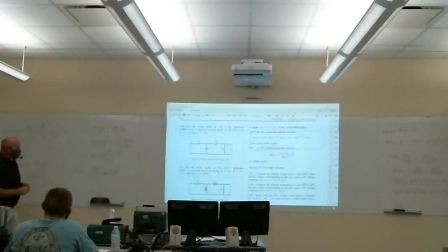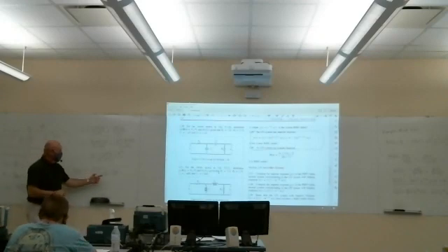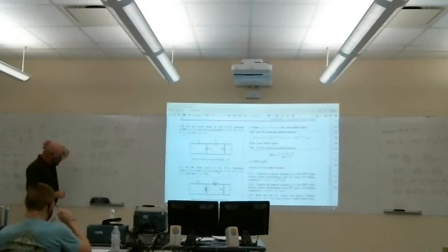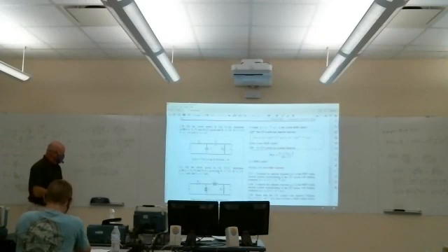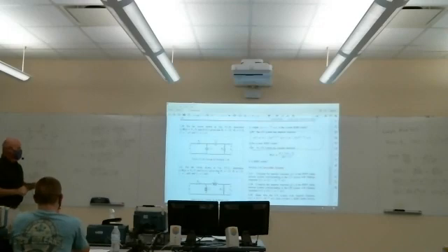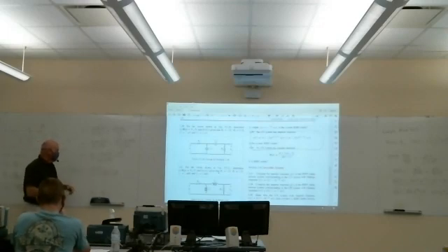That's the transfer function. We need to factor this, to see if we have real poles or complex poles. It's a second order polynomial in the denominator, so we need to factor that out, do the partial fraction expansion to get the h of t.